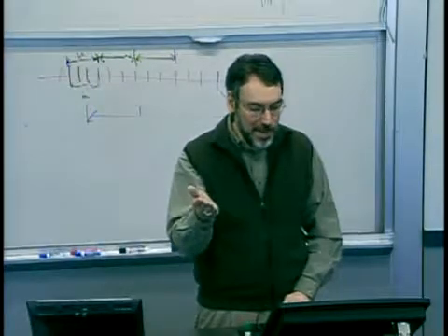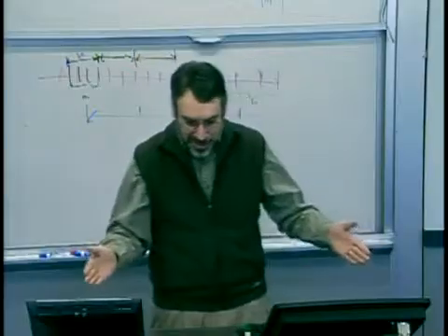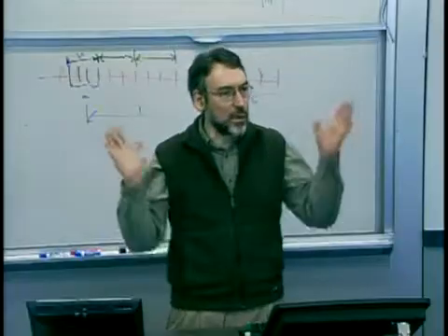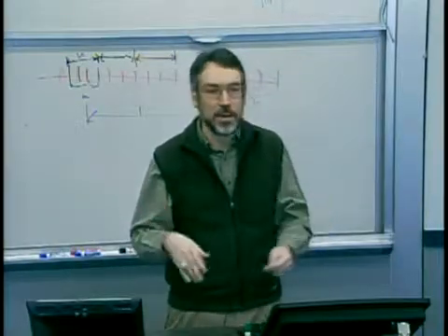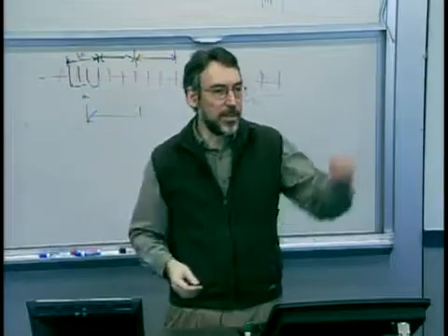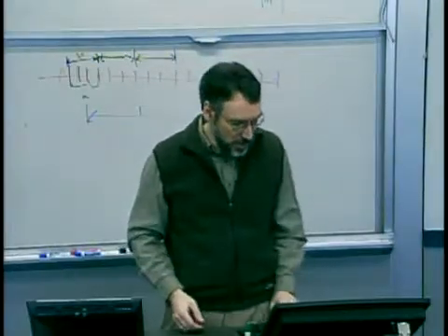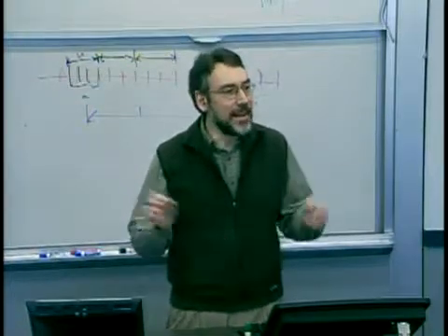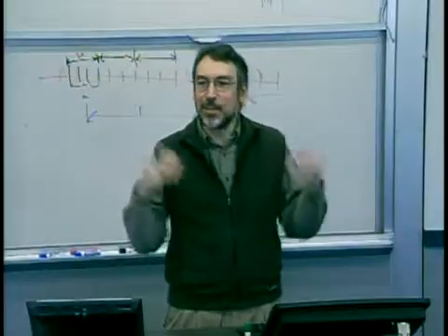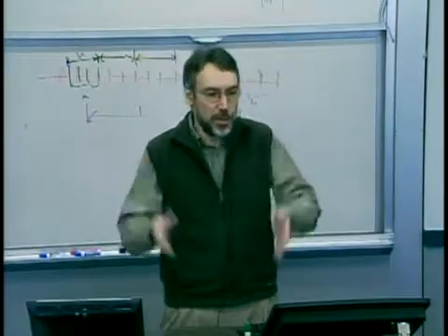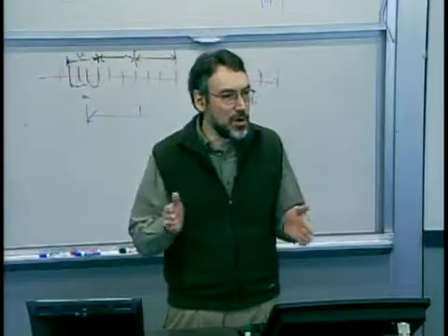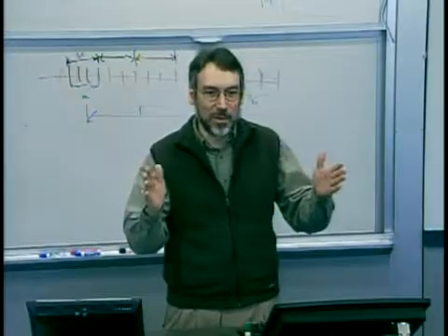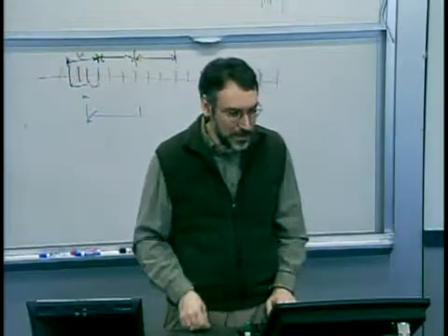And then we have an upper spec limit and a lower spec limit that we simply say, as long as the part dimension is within that range, we're going to call it a good part. And it meets maybe the design requirements, it meets our consumers' requirements, what have you. And what we're saying is, in essence, anything within those spec limits is equally good and equally shippable, right? So there's no notion of better or worse, it's simply an on-off decision, it's acceptable or not, okay? So that's a spec limit.